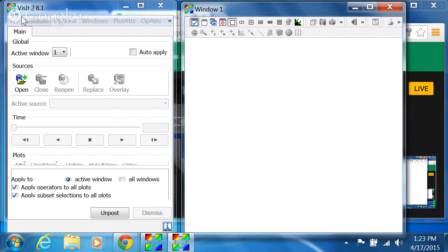I agree with what Anne mentioned. ParaView's GUI is probably more advanced looking than VisIt's GUI, mainly because VisIt, I think, strives to be a backend type, command-line processing tool to generate images. So it's very strong in that regard. You set up your Python script and you run visit -cli, and then it runs.